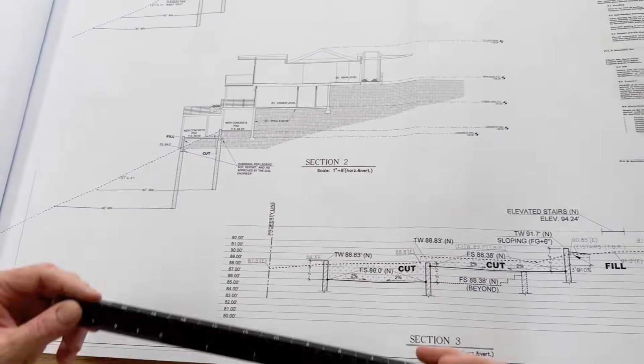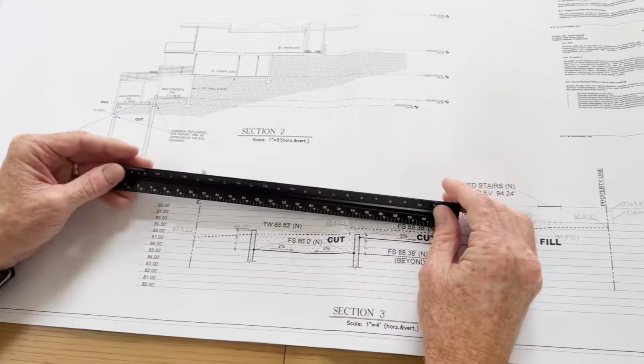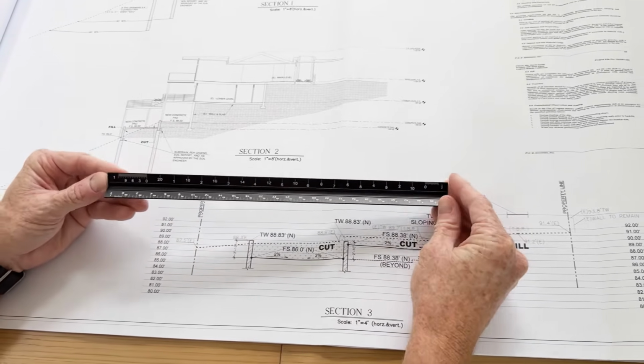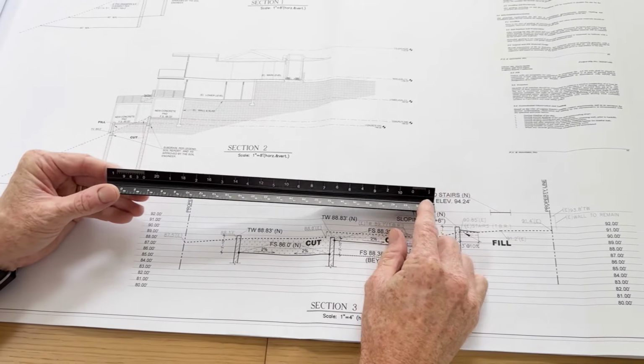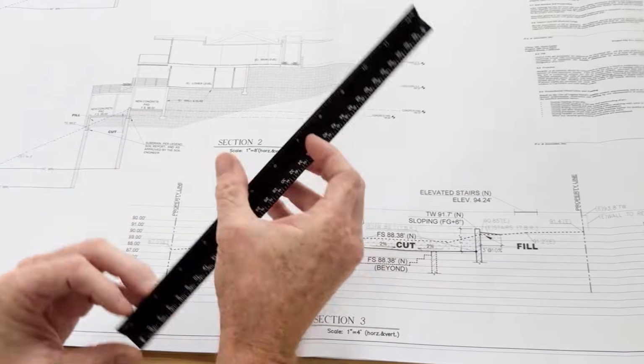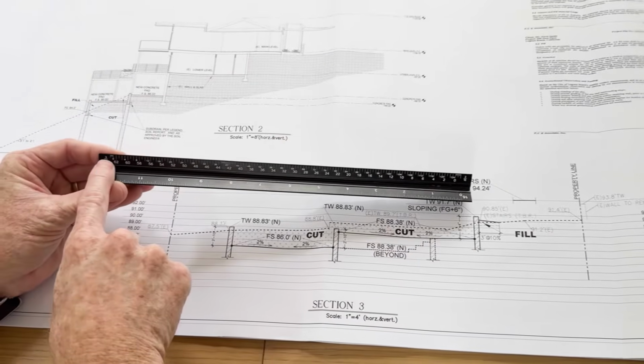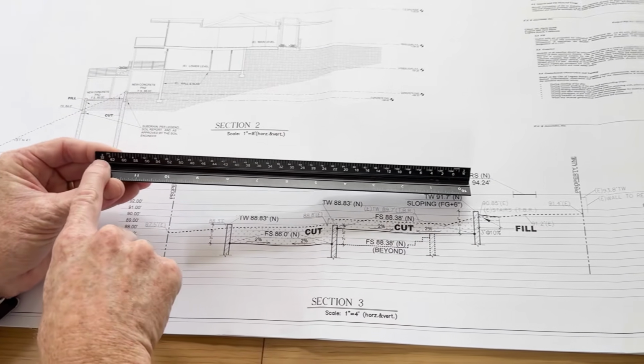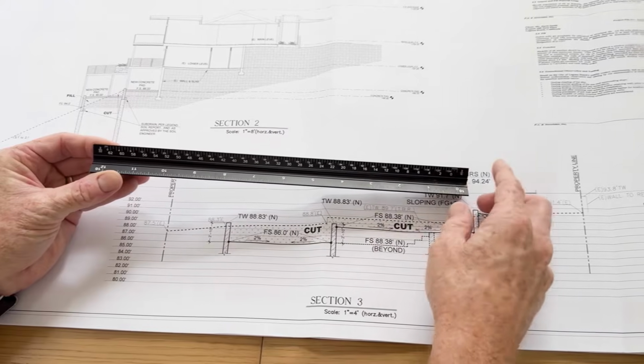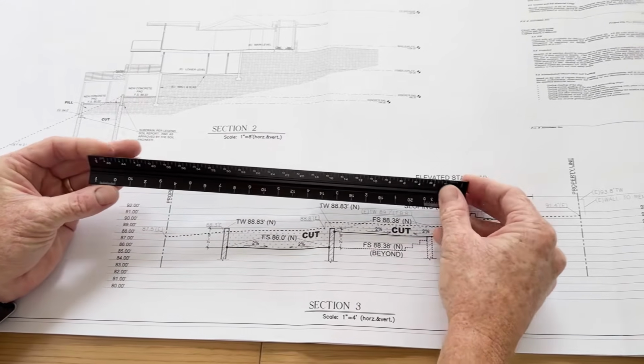So what I like to do is, a lot of times we have architectural rulers here, okay? These rulers are cool because they have lots of different options as far as converting. So in this case, we wanted to do 3/32 all the way up to 3/16. We could use that as an option.